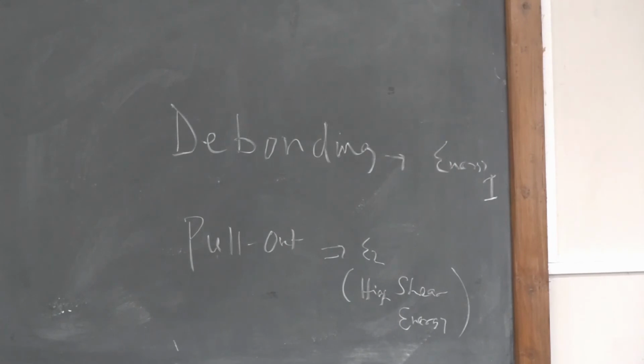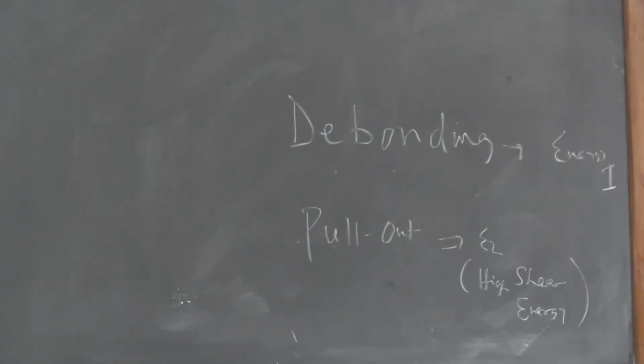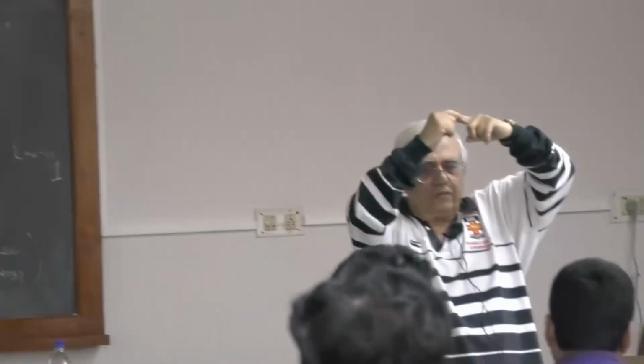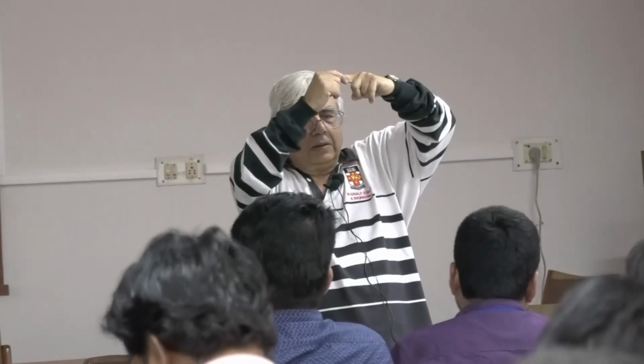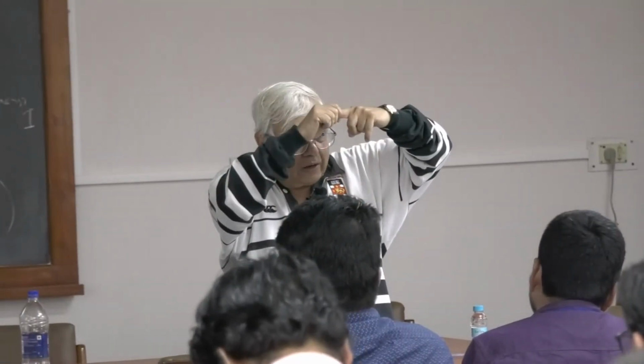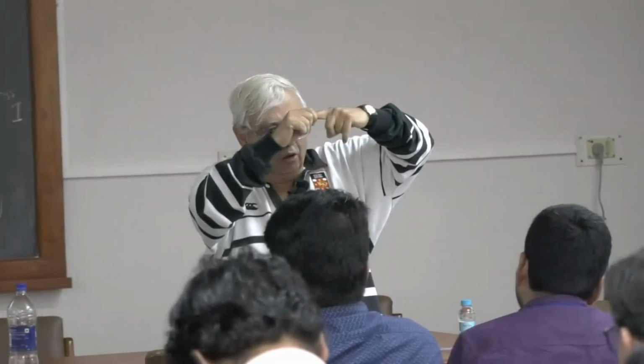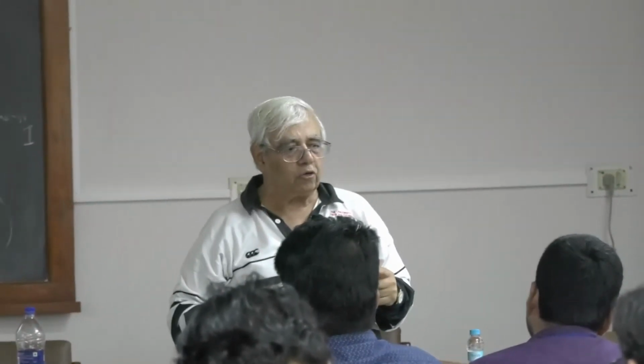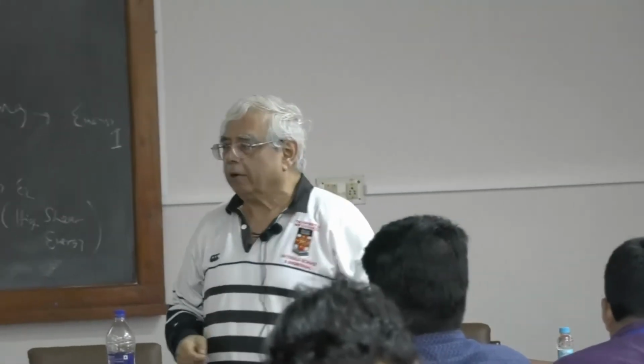If you can, all of you can do it this way. You have your finger and then have other 2 fingers on that, press it hard, and then try to pull up these 2 fingers like that. Because if it's bonded hard, it's taking a fair amount of energy. So all this impact energy you are giving to the material, instead of it going through and fracturing things, is being used up in shear, okay? So it's removing the shear. That's what is actually making the specimen much tougher.